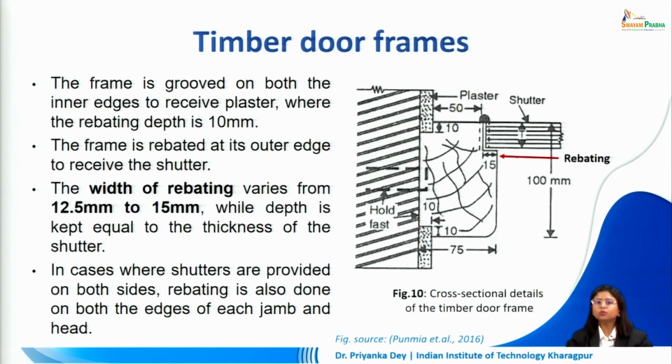The frame is grooved on both the inner edges to receive plaster. We can see here in the figure, a slight recess is provided. This can be up to a depth of about 10 mm and it will help us fix seamlessly the plaster next to the door frame.